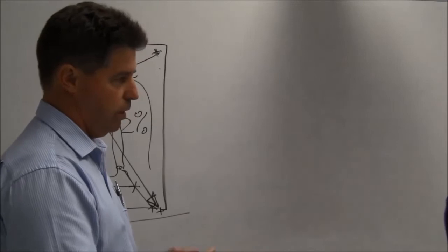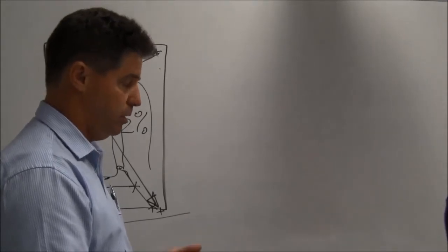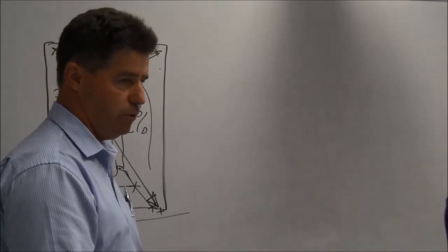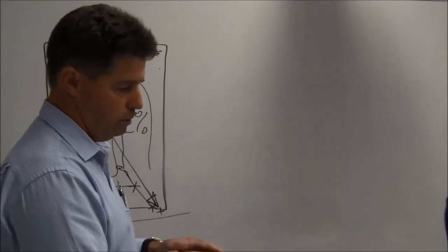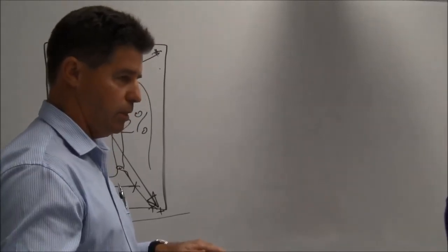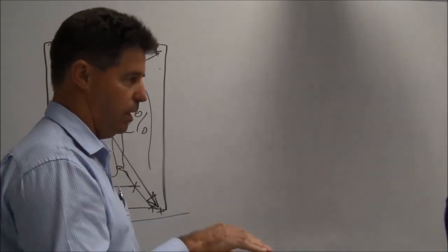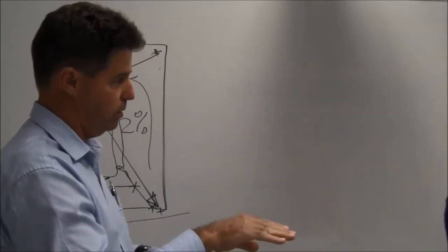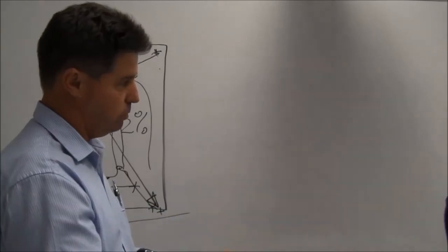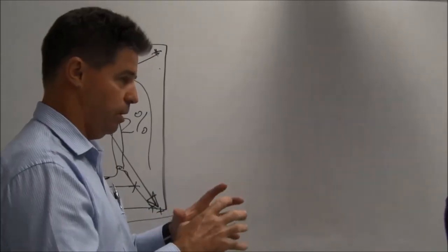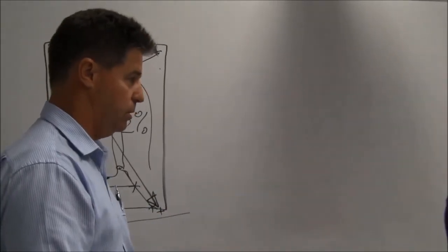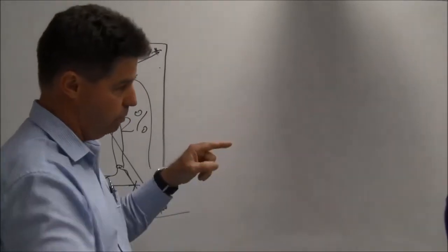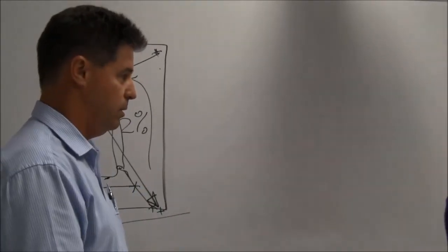It is important to understand that because when you're sizing the roofs and things, we only use 5 minutes. It's the time of concentration. It's fairly straightforward: hard surfaces straight off the roof, straight to the system. Once we get down though, we can start to look at the tables on the ARIs and come back. Instead of going 5 minutes, we can go all the way down to 14 minutes, and the rainfall intensity reduces quite a bit, so we can reduce all our pipe sizes and everything else to suit. We don't have to use 5 minutes all the way through the system.